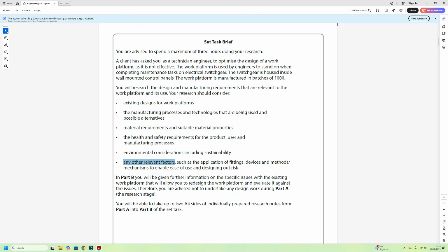You can clearly see that nylon does not have any mechanical grip on any surface. We make nylon bearings out of them. They're not fast-running bearings, but we do make nylon bearings as such. But if you change the casters or add casters which have a rubber tire, you're going to have a lot more mechanical grip on there. Some of these casters have built-in brakes, so that would be fantastic. If all four wheels have brakes on, fantastic, job done. If you use four wheels which have their own brake, you can now see that actually that's not going to go anywhere.